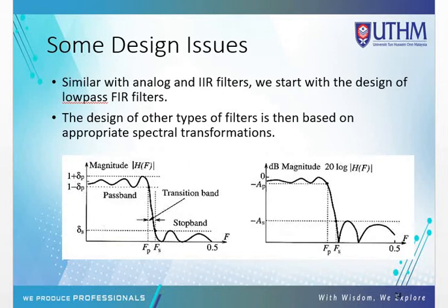Hello everyone, in this session I will share with you some design issues of FIR filter design. FIR filter design starts with the design of the low pass filter. The design of other types of filter is then based on the appropriate spectral transformations. This means that if you want to design a band pass or high pass filter, it is based on the appropriate spectral transformation to transform it to the high pass or band pass. But we must start from the low pass filter first.